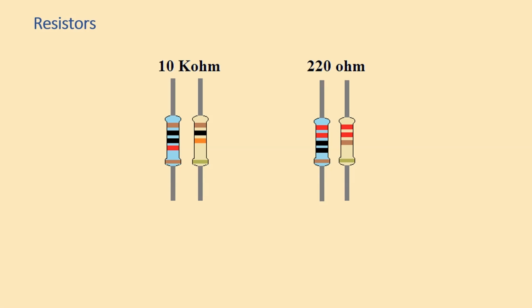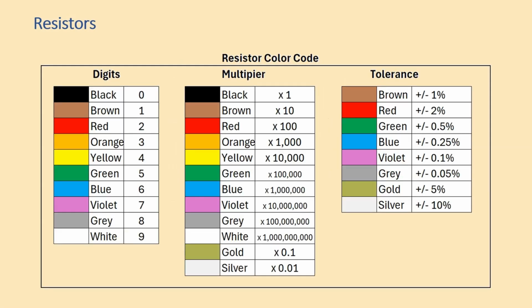Anyone who has worked with resistors knows that most resistors are color-coded to indicate their resistance and their tolerance. And it is the colored stripes that make the difference. These colored bands are found on the body of the resistors and follow a standardized color code scheme. This chart titled Resistor Color Code is a reference for this color code scheme to determine resistance values and tolerance.